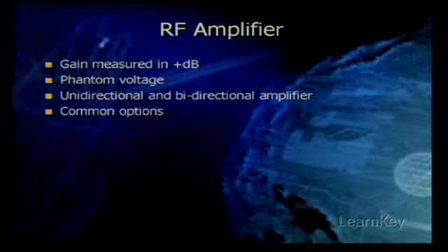Frequency response is likely the first specification that you should decide upon in this case. If a wireless LAN uses a 5 gigahertz frequency spectrum, an amplifier that only works in the 2.4 gigahertz spectrum is definitely not going to work in that situation. So determining how much gain, input, and output power is required by performing math calculations prior to purchase of an amplifier is your best course of action.